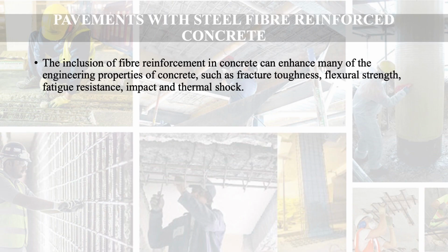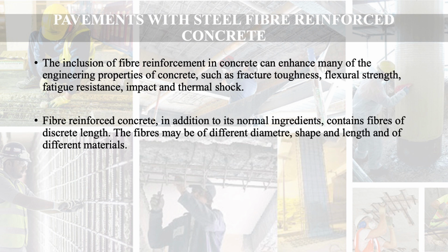The inclusion of fiber reinforcement in concrete can enhance many of the engineering properties of concrete, such as fracture toughness, flexural strength, fatigue resistance, impact and thermal shock. Fiber reinforced concrete, in addition to its normal ingredients, contains fibers of discrete length. The fibers may be of different diameter, shape and length and of different materials also.